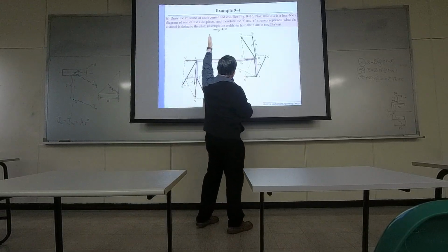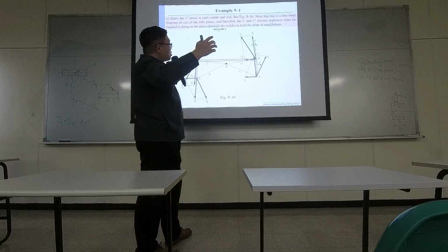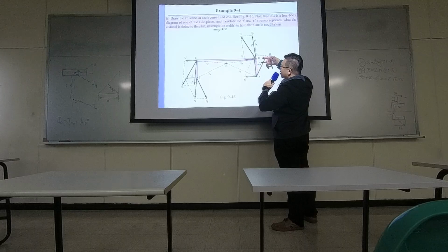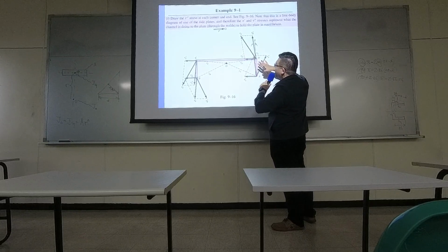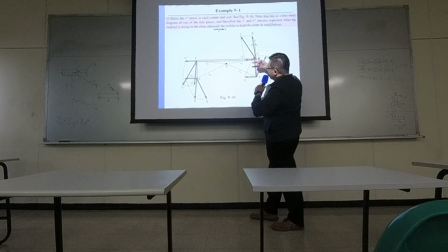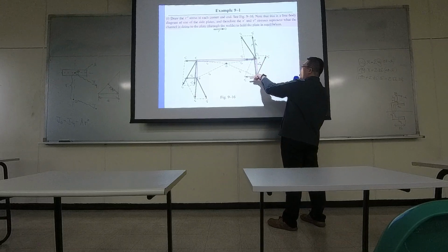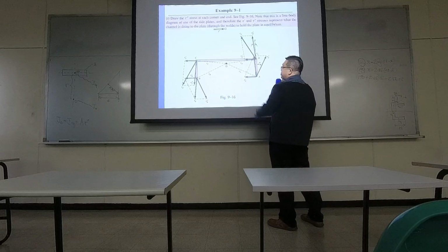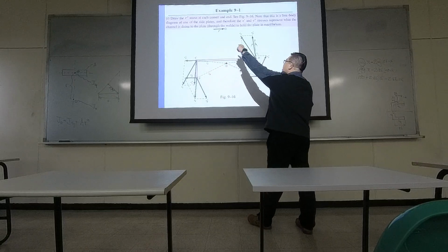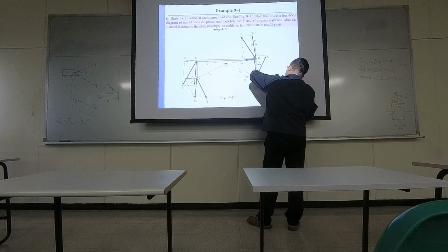Due to this horizontal external force, there would be a reactive shearing stress fighting against the normal force, so going left. So we are now talking about shears due to reactive forces. So at all four corners, there are exactly the same horizontal shearing stresses going left. But at ABCD corners, this external force is going to have this clockwise moment.